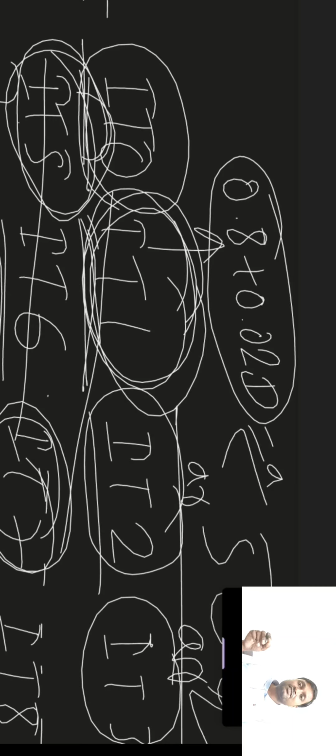In preferred series we are not multiplying exactly with 1.6; that is why they are called preferred series. Now we are multiplying exactly with R, so the standard tolerance grades from IT 1 till IT 5 are arranged in an exact geometric series.